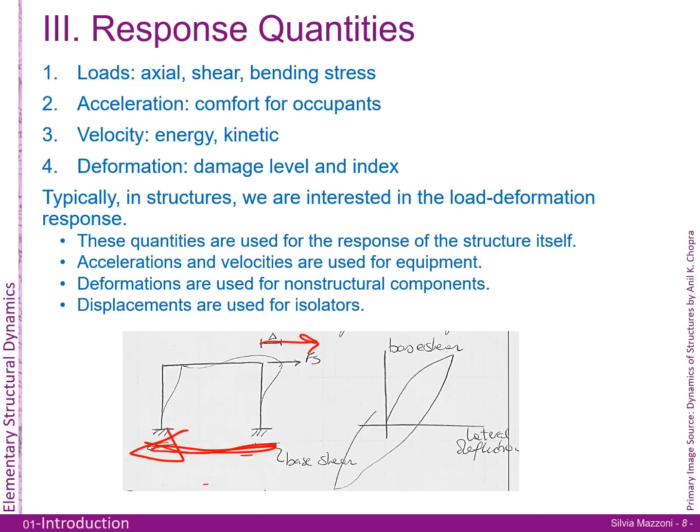You really want to minimize your deformations because that could actually lead to very, very expensive problems with your non-structural system. Most important, for example, is your sprinkler system. You need to have an understanding of what the deformations are going to be in your system so that you can define and design flexible joints in your sprinkler system or HVAC system or other non-structural components in your structure. And also displacements are used for isolators. You want to estimate displacement so that you can design your base isolators, whether it's for equipment isolators or for your structure appropriately. And those are based on displacement capacities.